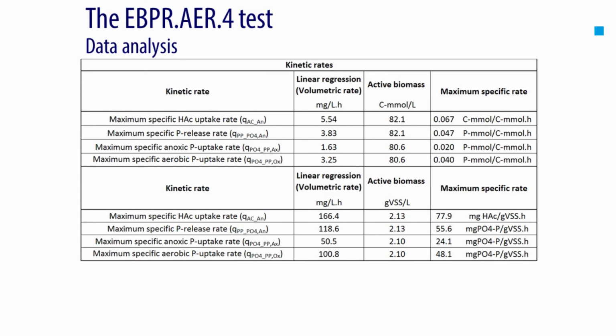Whilst these values provide an estimation of the aerobic and anoxic activity of PAO and DPAO, the rates need to be carefully assessed, taking into consideration the potential effect or influence of the environmental and operating conditions that were used for the execution of the batch activity test, as discussed in section 2.2.8 of the textbook. Other operating, environmental and even microbiological factors may need to be assessed if the results differ considerably from the previous data reported in literature.